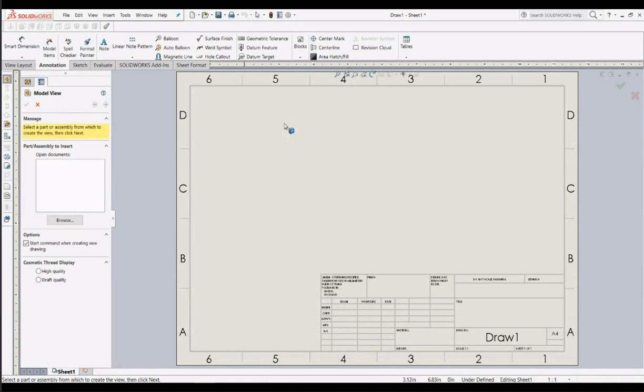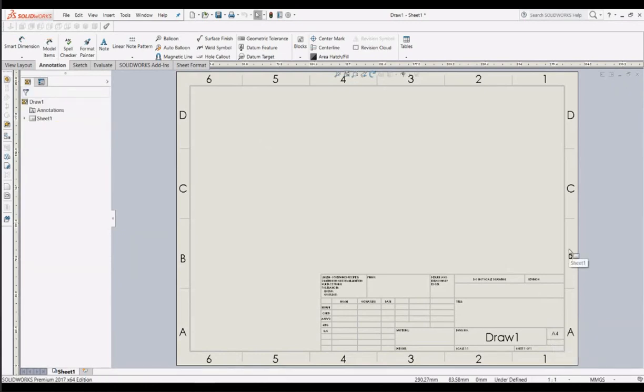Okay, as I mentioned before, after opening every document, we have to do one thing first. That's the first and foremost thing that we have to do after opening a document in SolidWorks. That is assigning our standard unit system. We have to change our standard unit system. So our standard unit system is millimeter, gram, and second.